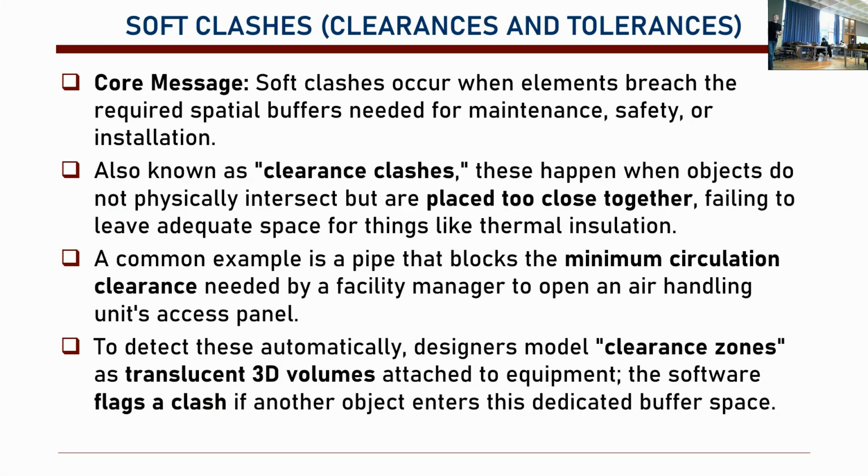A soft clash is a clearance and tolerance clash. In a soft clash, basically, for an element we need a space, and we need that space for maintenance, safety, or installation. I'll show you a clearance. If you look at the pipes above, they are about 10 centimeters away from the structural system.